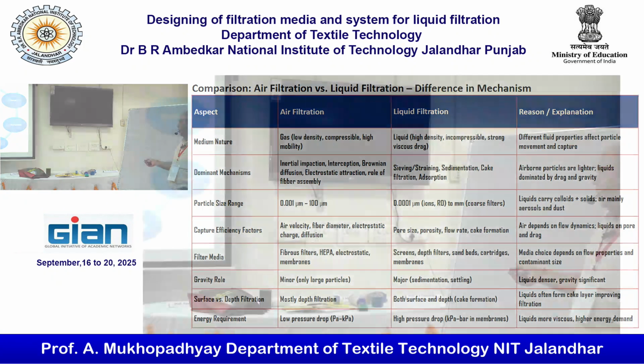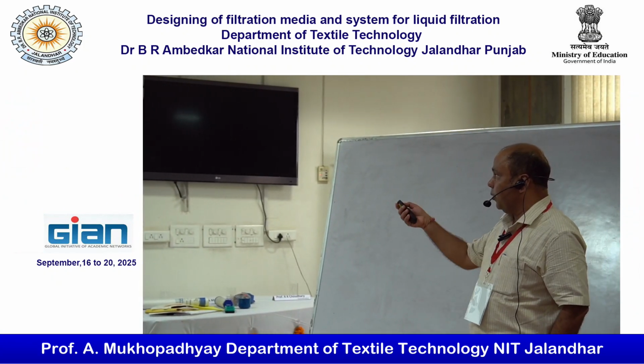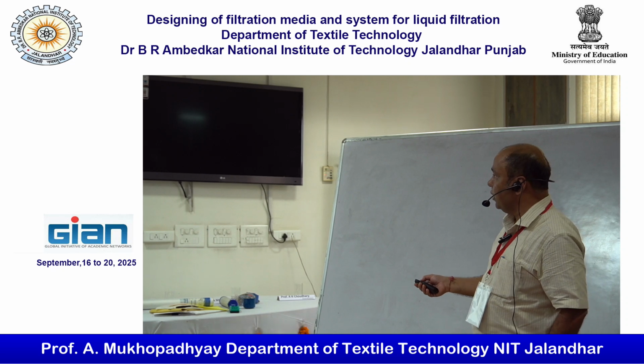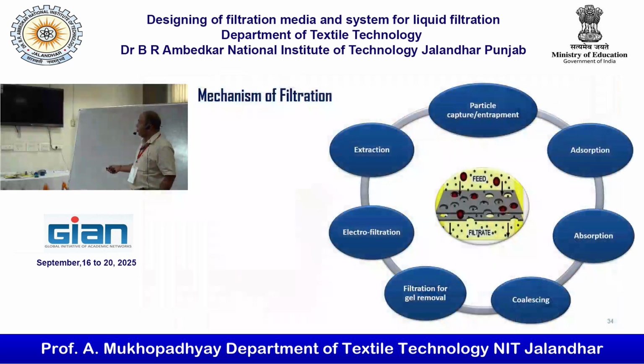Now, the mechanism of filtration. If you see the broad aspect, it is not restricted only to particle capture and entrainment, because mostly we talk about particle capture and entrainment whenever we talk about liquid filtration. But it can also have absorption phenomena, coalescing, gel removal, electrofiltration and extraction. We will see one by one. So this is the solid-liquid filtration where we remove the particles.